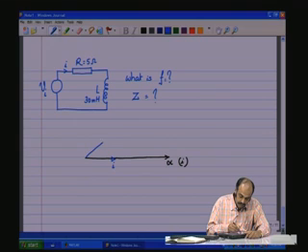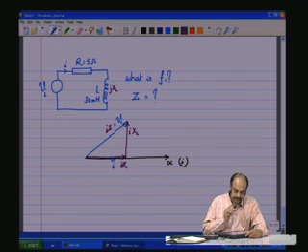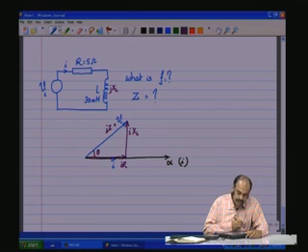So, the voltage has to be in this direction, and let us say that is your voltage V. There are two vectors, one in phase with the current, which is I into R, and the other orthogonal, which is I into XL, because this contributes jXL into I, which is going to cause an anticlockwise 90 degrees rotation, and this is equal to I into Z, and there is an angle theta of course here.